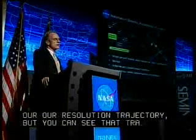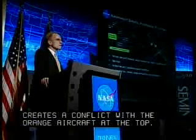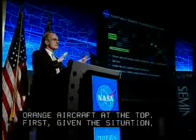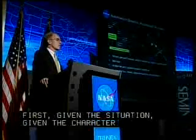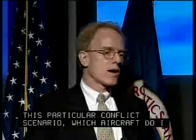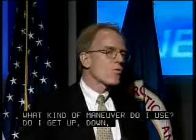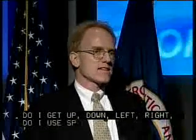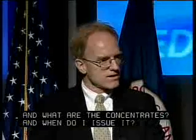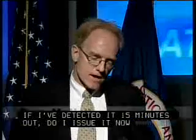So what the automation needs to do is first decide, given the situation, given the characteristics of this particular conflict scenario, which aircraft do I move? What kind of maneuver do I use? Do I go up, down, left, right? Do I use speed? And what are the constraints? And when do I issue it? If I've detected it 15 minutes out, do I issue it now, or do I wait until it's 8 minutes out? And this depends on a lot of factors.